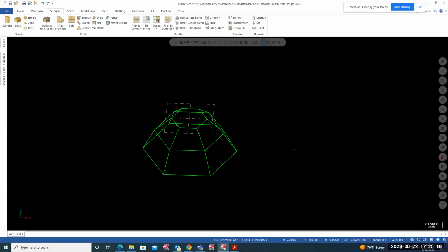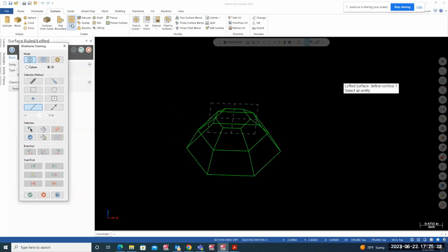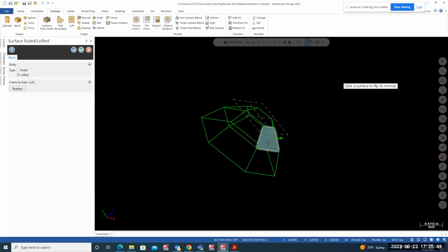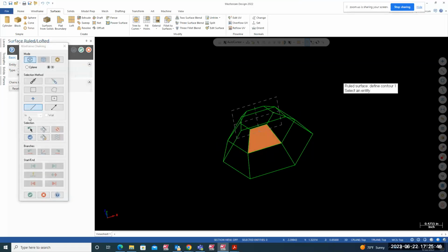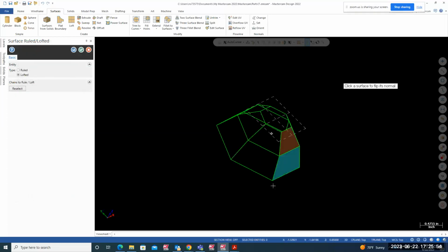So to do the surfaces, go surface, loft. I can go single, this one. We can pick this entity also. Start point, end point are same. Start, end point is same. So I can go single, pick this one or this one, same thing. There. Or you can go single, this one and this one, same thing, because endpoints are same. Open that.